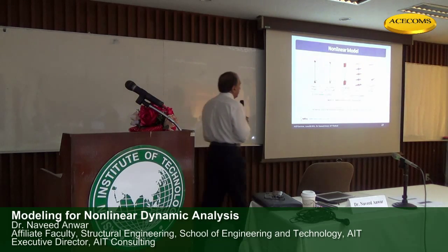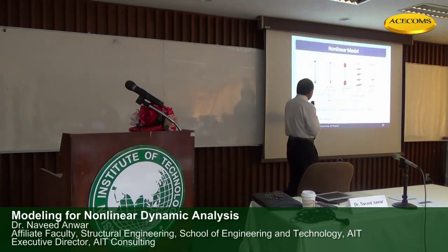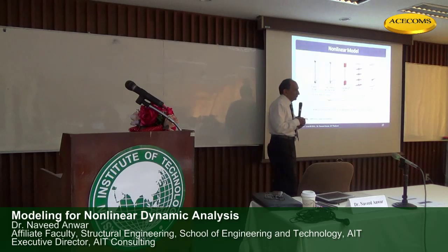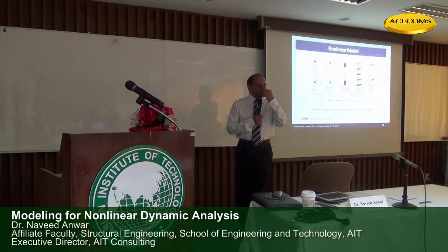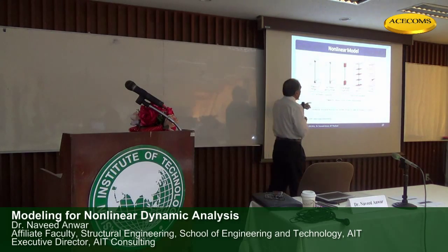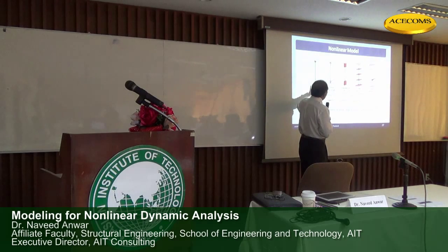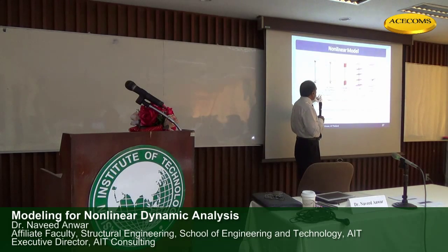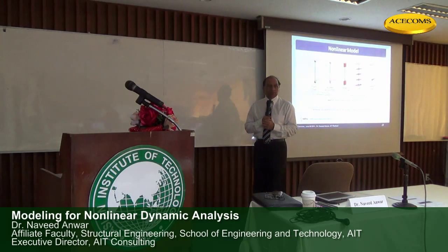The nonlinear model, again, could be taken from this one. This is an excellent document: the Seismic Design Technical Brief number 4 from NEHRP. Here they summarize what type of nonlinearity modeling we can do. Basically, concentrated plasticity or distributed plasticity. Those two approaches can be used.